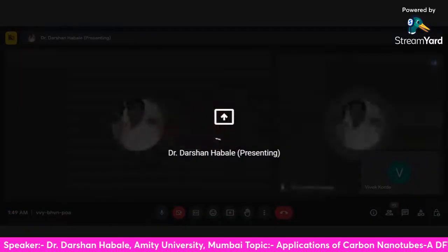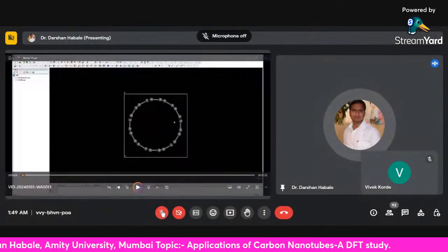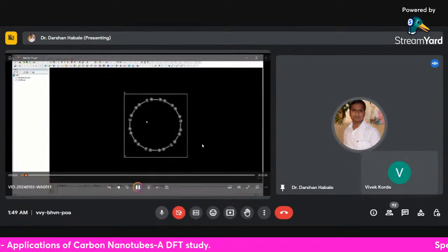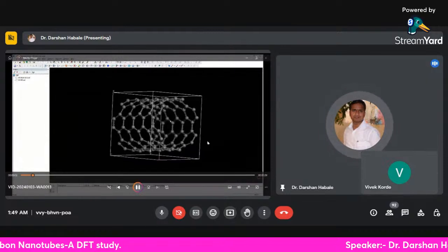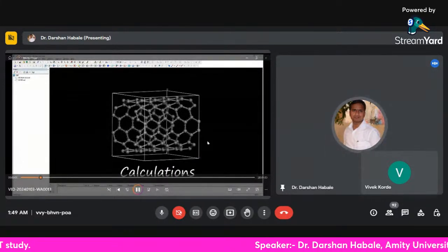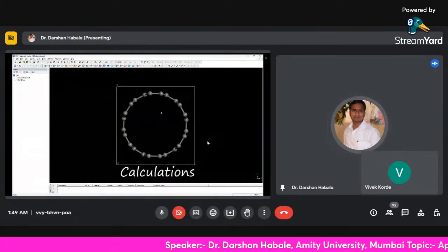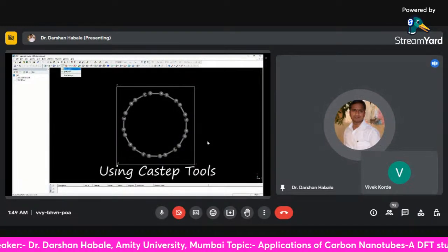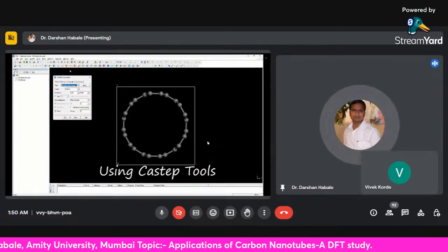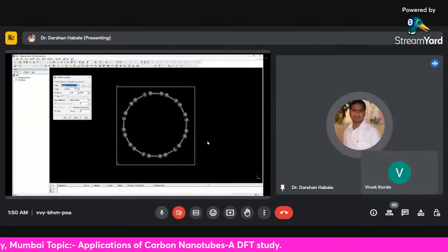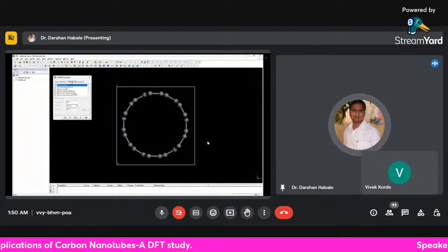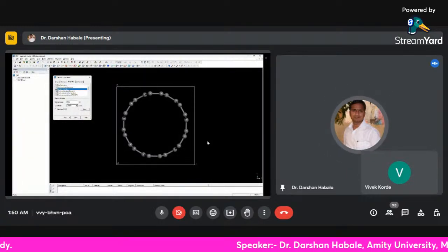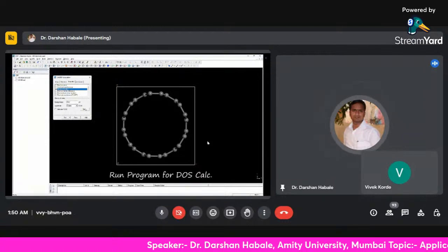This is if you want to run the program. This is the sample video to run the program. Here we have a carbon nanotube system. So we go to the CASTEP tool. Just click on the CASTEP tool. Move to the calculation part. Here there are tasks. You can go to geometry optimization, you can go to energy, you can go to density of states.